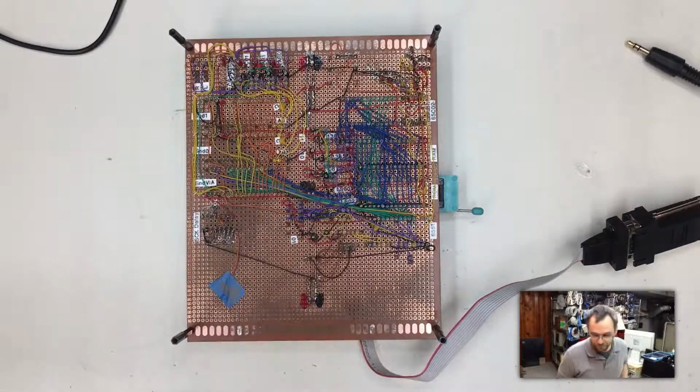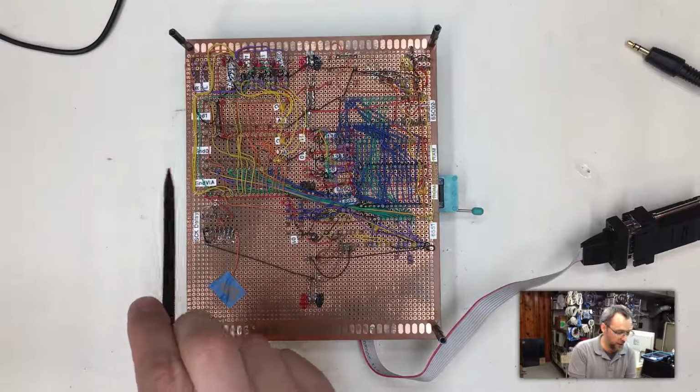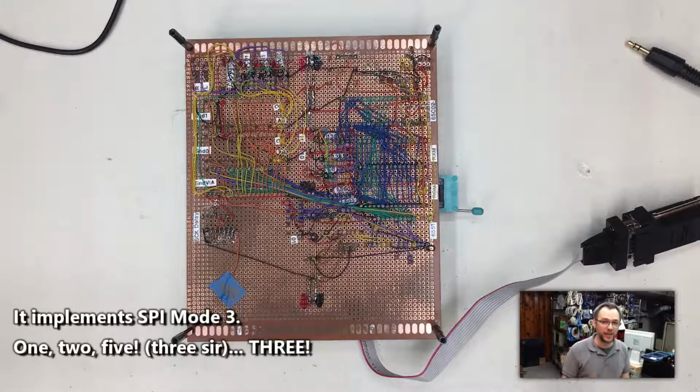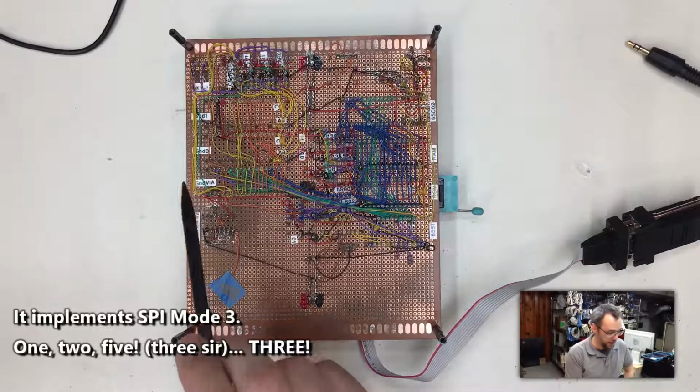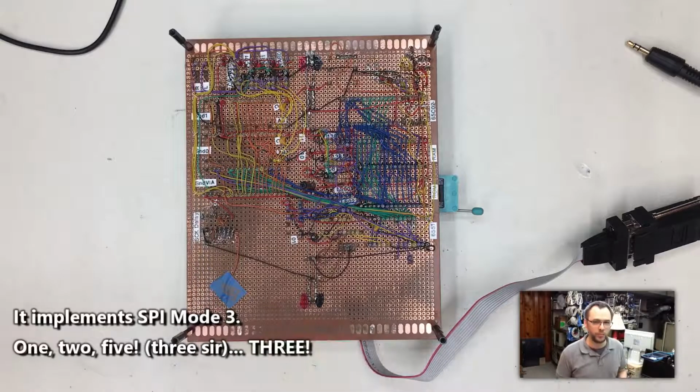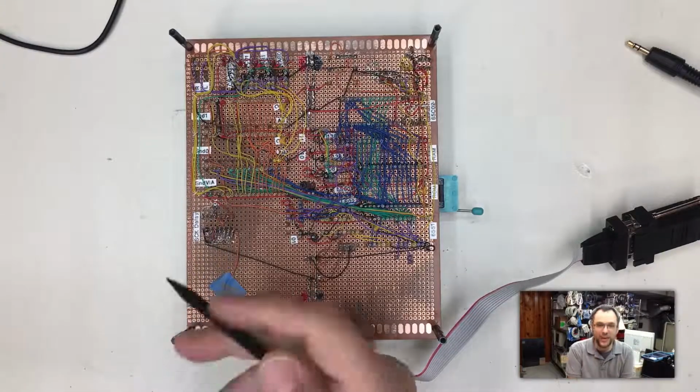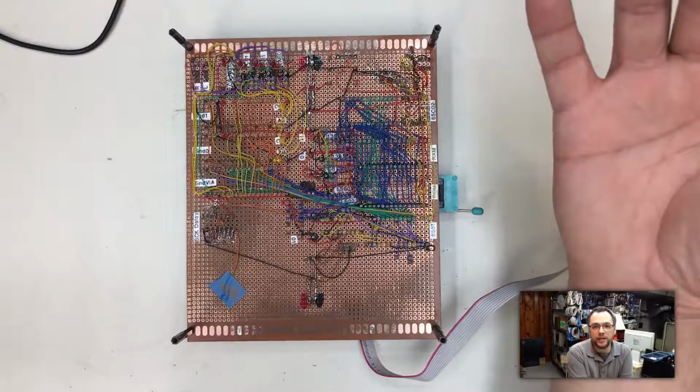Now on the VIA, this effectively almost directly implements SPI, but it's kind of like SPI mode 1, and most SPI chips support SPI mode 0 or 3 for whatever reason. So in many cases with the sound VIA here, you can't connect it directly to an SPI device.